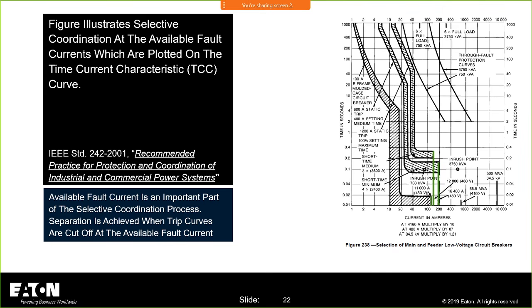I see a question: are conductor damage curves insulation damage, termination damage, some combination? They are insulation damage. What we use are the ICEA equations to establish that. It doesn't give you the termination. You always have to follow the National Electrical Code to make sure you're applying the conductor correctly. That damage curve is the thermal capability of the insulation on those conductors, and that's the limiting part, right? If you think about a conductor, I have the annealing damage for the conductor itself, where it deforms and whatnot. I may have loose terminations.